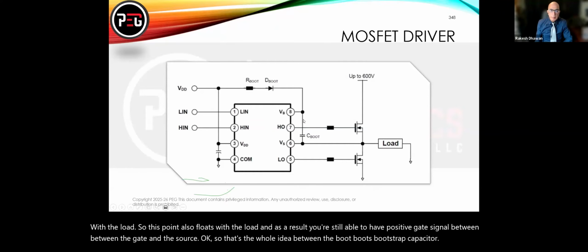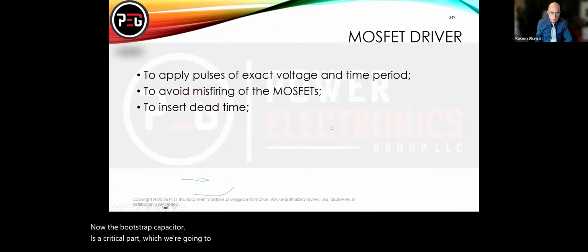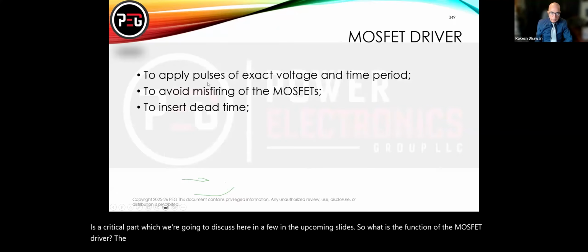Now, the bootstrap capacitor is a critical part, which we're going to discuss in the upcoming slides. So what is the function of the MOSFET driver? The MOSFET driver has to faithfully apply pulses of exact voltage and time period, and avoid misfiring of the MOSFET.